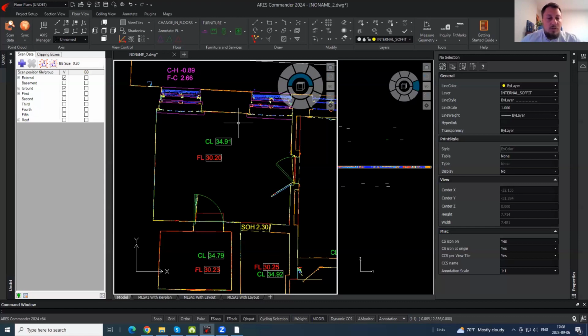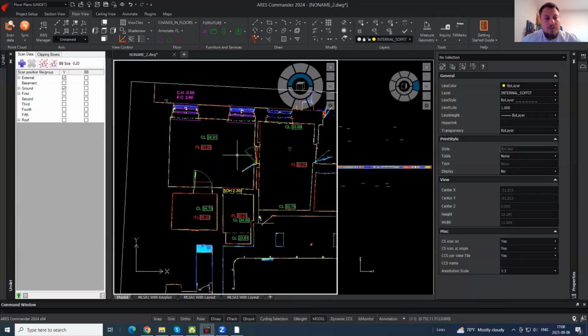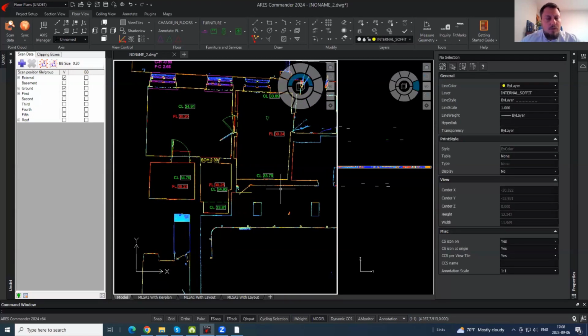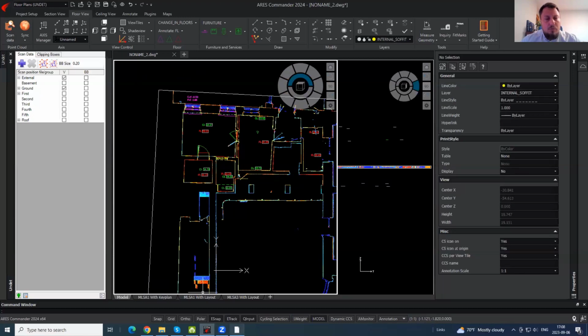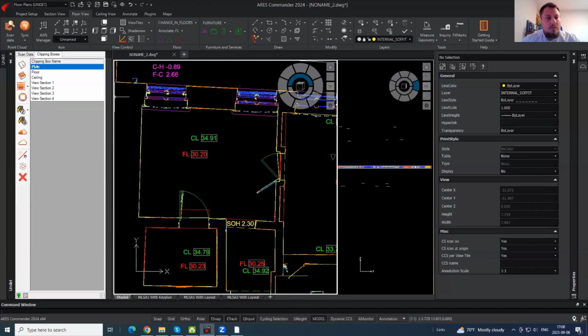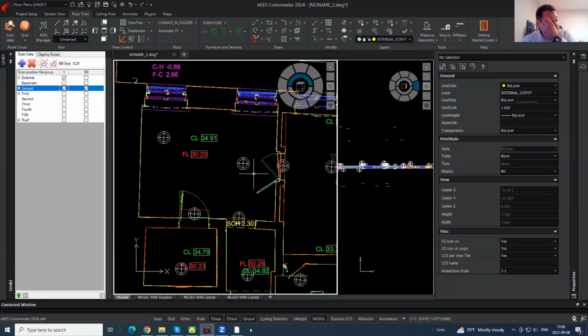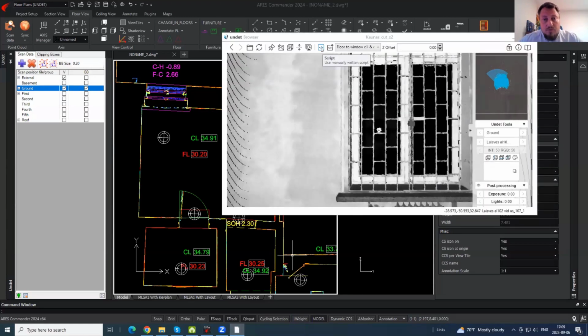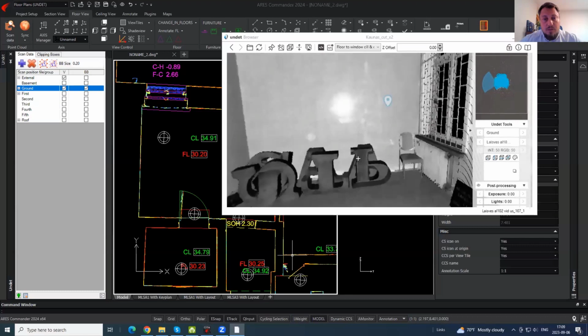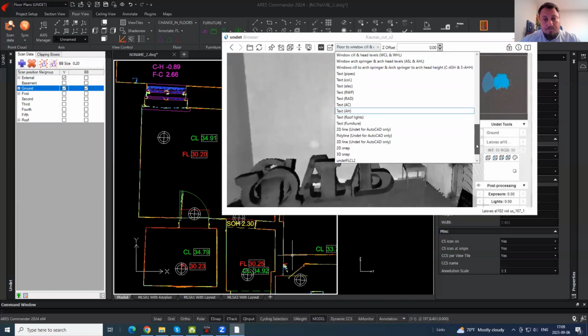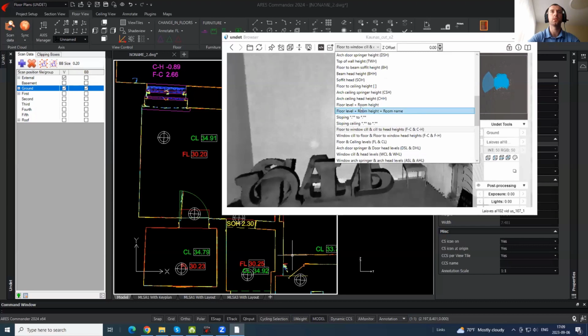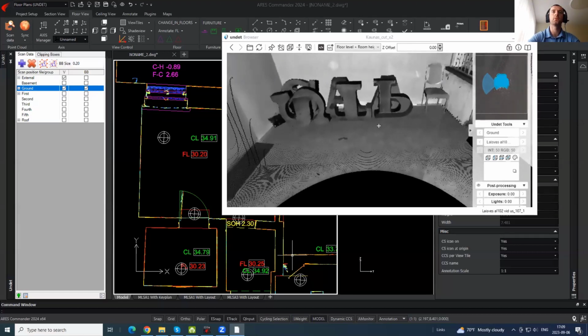So in this case, we showed a little bit of both annotation processes. Maybe you can show one more script, for example, how to annotate the room height and floor levels with 2 clicks. Yeah, let's try using Undet browser. In Undet browser you will find 50 plus scripts to annotate your drawing, so you just need to find it. Floor level, room height, and room name. So let's pick and just pick floor and ceiling. Just catch the point.